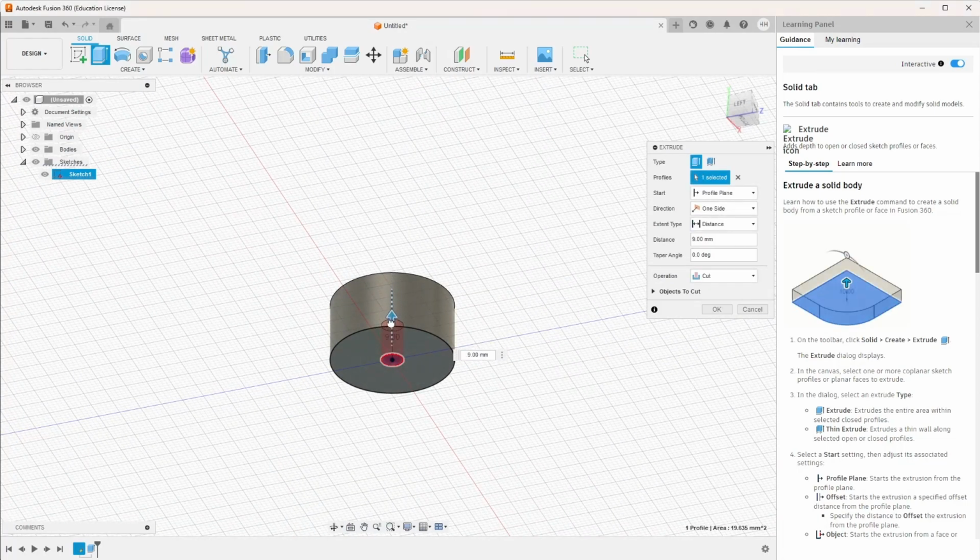That's one option. I can drag my hole, and I can type in numbers. I can also use this drag to taper or change my hole. So if I wanted to taper it in one direction, like make the hole bigger and bigger, I could use this and create a taper with 5 degrees or 10 degrees. Now I don't want that, but I could make the hole smaller and smaller so my axle enters but then gets kind of stuck on the way in. I don't think I'm going to do that.